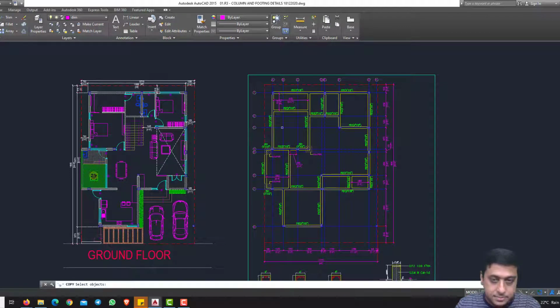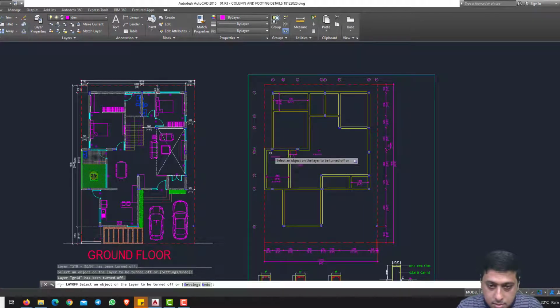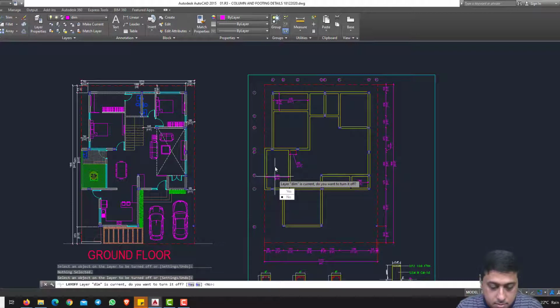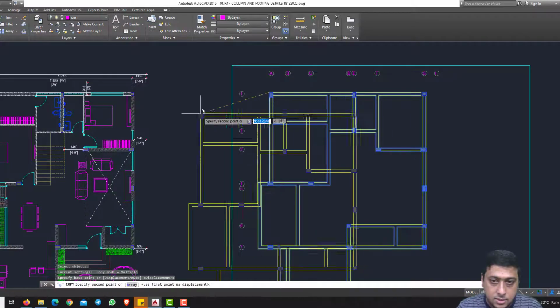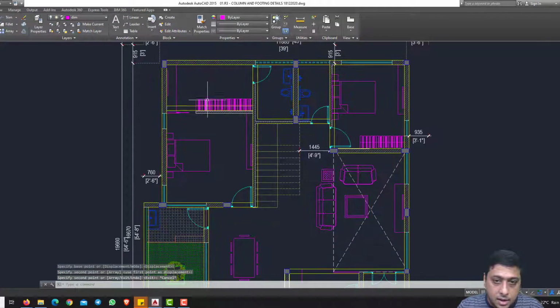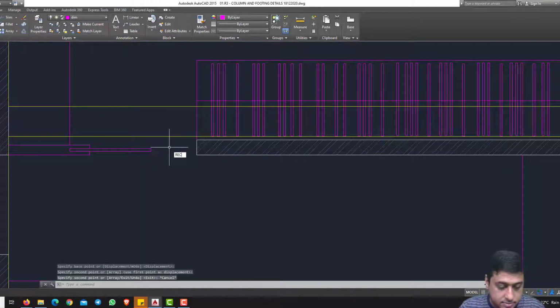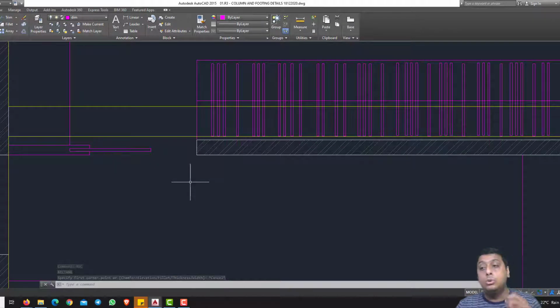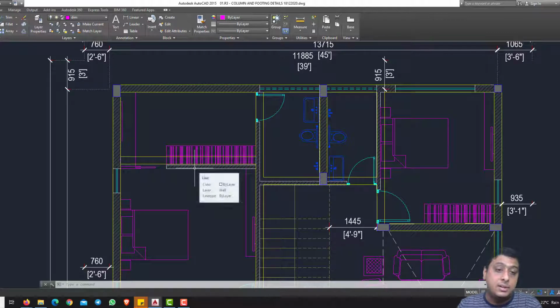If I overlap this, I'll just layer this up. Just overlap this to this. If you observe here, I can see these yellow lines. Okay. Can you see here? It is actually missing. This wall is coming outside and this beam is inside. To show this difference, I have intentionally done this, so that we can understand what the problem is between the drawings and the site.